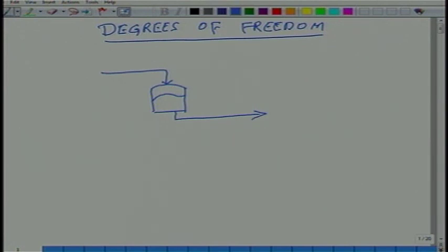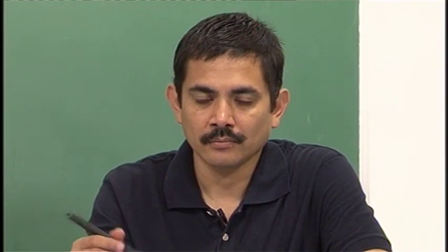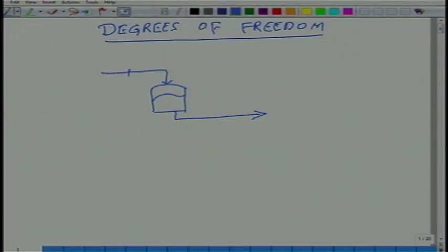How many independent valves can you put in? No, I am not talking degrees of freedom, we will come to degrees of freedom later. How many independent valves are there for this simple process? One feed in, one feed out. How many valves will be there? Two valves, one at the inlet, one at the outlet, right, okay.